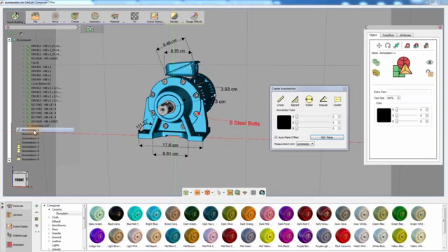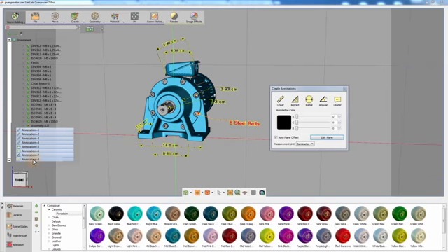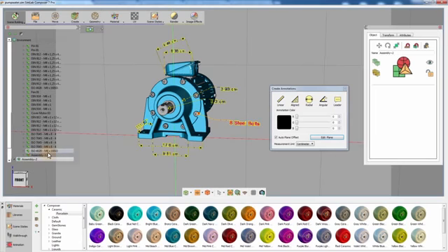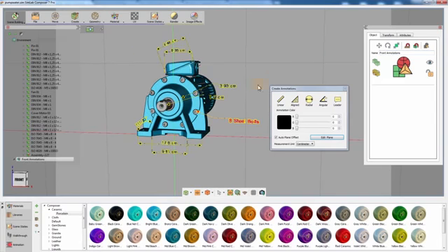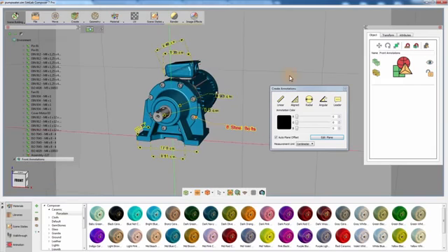In the Object Tree panel to the left, select all the annotations you have created. Then right-click and select Create Parent. Change the name of the newly created group to Front Annotations. Arranging the annotation into groups allows you to have better management and control over those annotations. Hide the first annotations group by clicking on the visibility icon, or by pressing H on your keyboard.